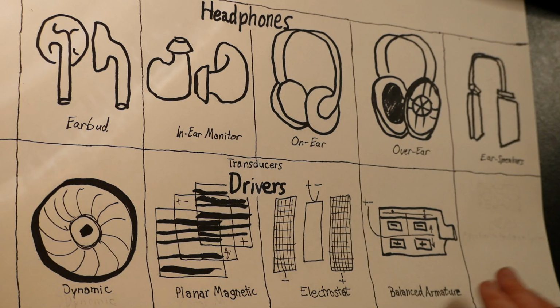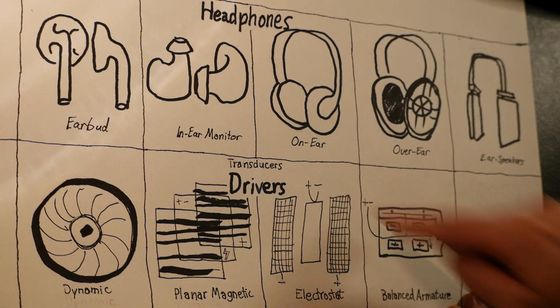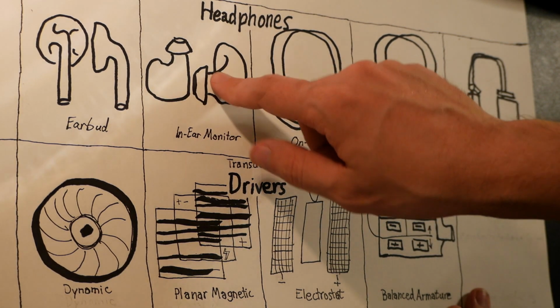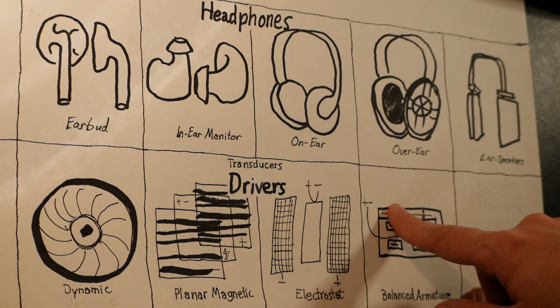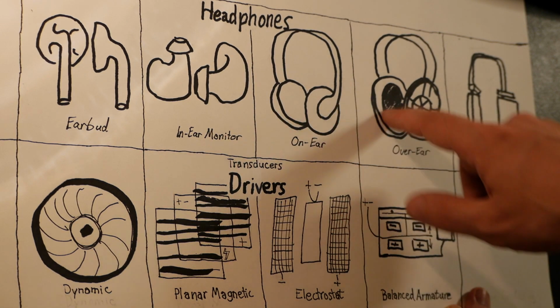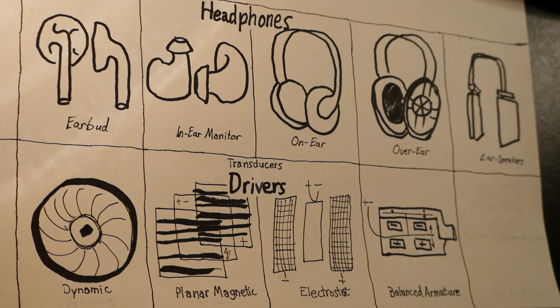And also like a planar magnetic, that wide plate on top always stays level as this arm moves up and down, so you don't have any modal distortion. So the balanced armature is extremely compact and low power usage, so we can easily fit it inside of an in-ear monitor headphone. However, it doesn't displace very much air, so it doesn't create the volumes we need for the larger headphones, at least not by itself.